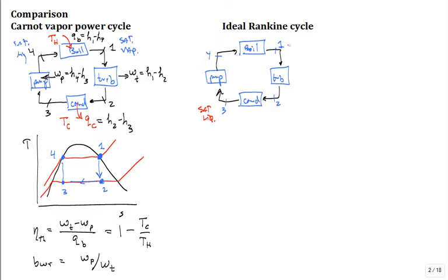And then out of the boiler, we'll still have saturated vapor. So we still have our main heat transfers, and the Q in the boiler is still the difference H1 minus H4. The work out of the turbine is still H1 minus H2. The heat transfer out of the condenser is still H2 minus H3. And the work into the pump is H4 minus H3. We still use those equations to calculate those primary work and heat transfers.